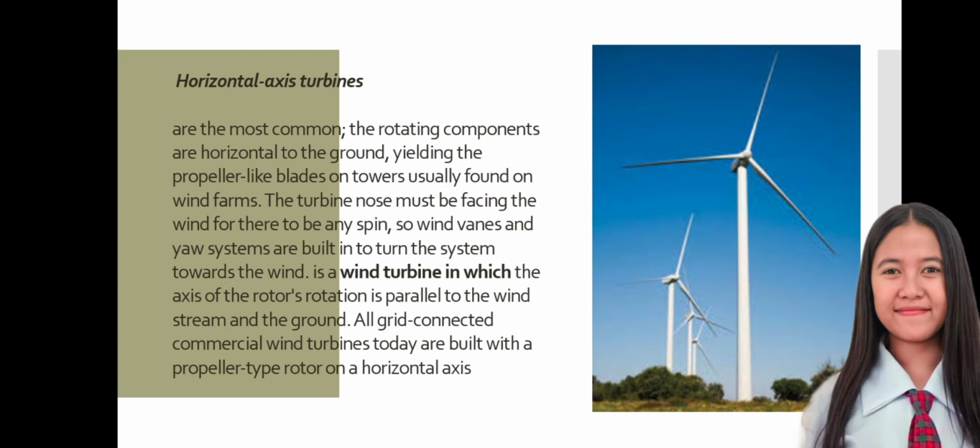The horizontal axis turbine needs the wind to flow at the right angle to the blades. If it blows from a different direction than the blades are facing, the turbine gets much less energy from the wind. To accommodate changes in wind direction, the turbine has a yaw drive that rotates the unit's direction. However, the drive adapts slowly in changing directions because it must turn the entire turbine and propeller assembly.